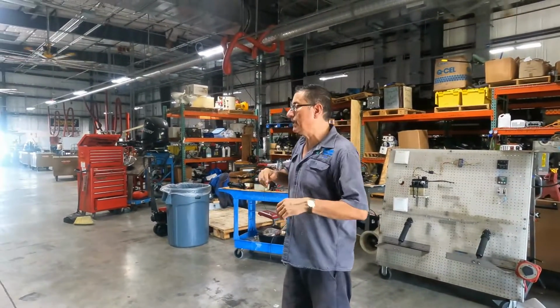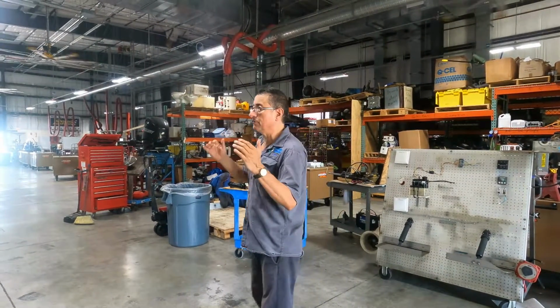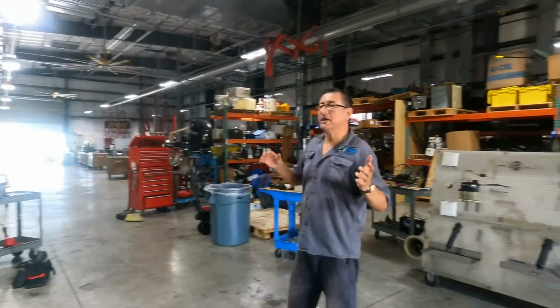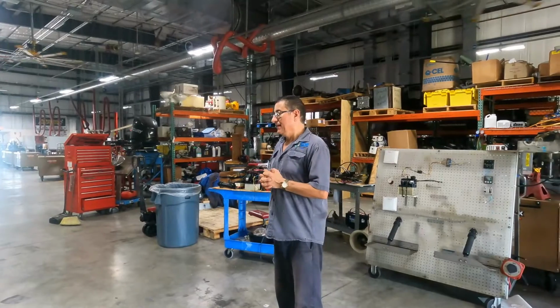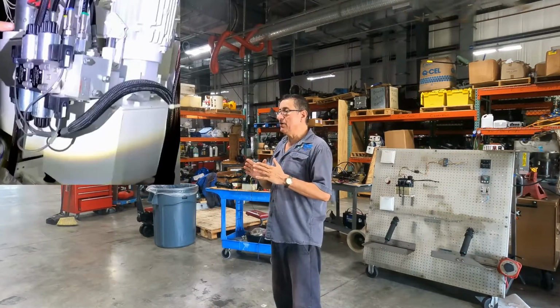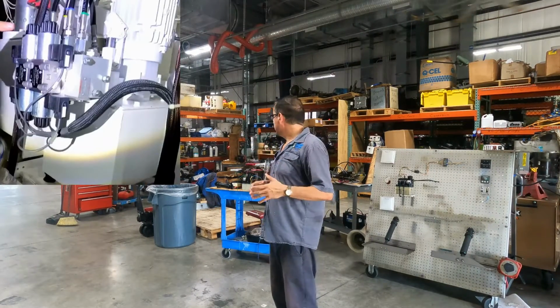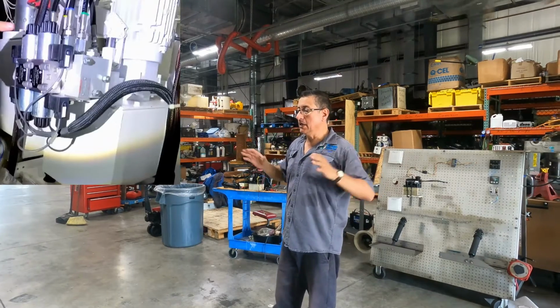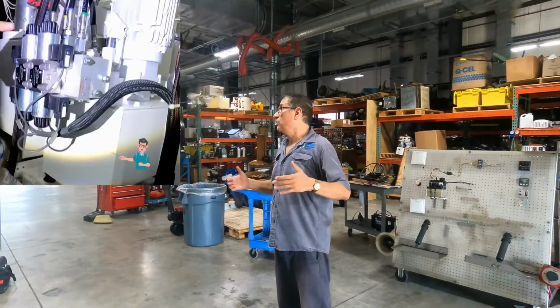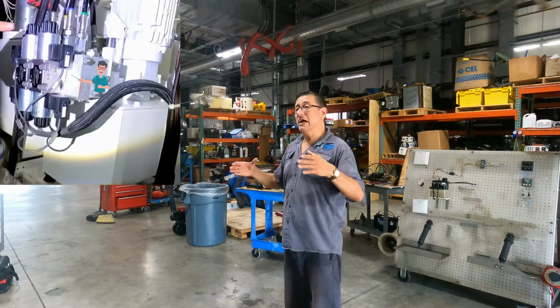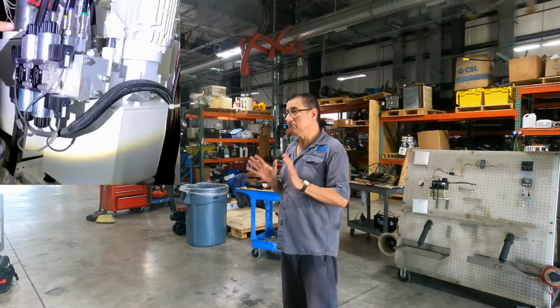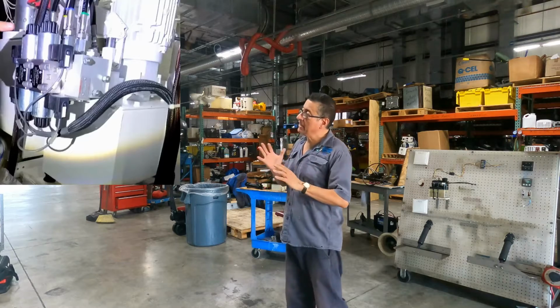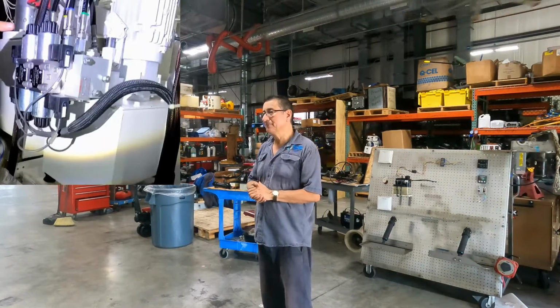We are going to quickly refresh the concept of the different hydraulic systems in your boat in a central hydraulic unit. The central hydraulic unit, like I explained yesterday, is composed of the container or reservoir, the servo valves, the motor, and the pump. And the motor could be AC current or DC current.